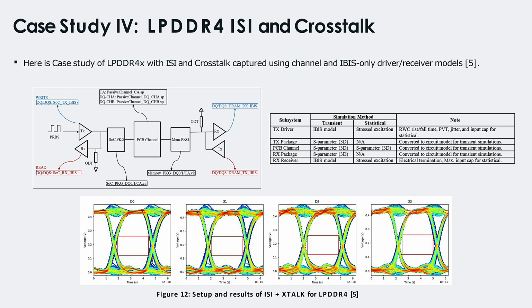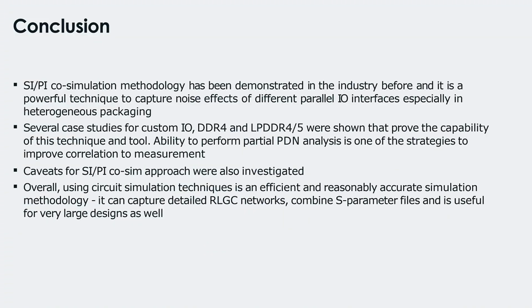And once you're getting the models, you start to bring in the accurate models. It could be IBIS, IBIS-AMI, or the transistor level that we discussed earlier. So that would be an angle that we would like to highlight here: if those models are not ready, there are some techniques where you stress your eye and then try to design for that stressed eye. And I think with that, I'll turn it back to Janani to wrap up the session.